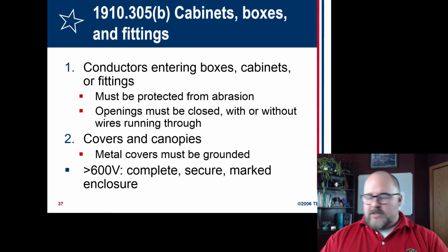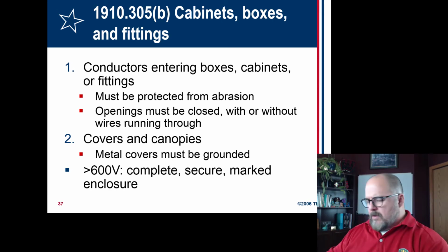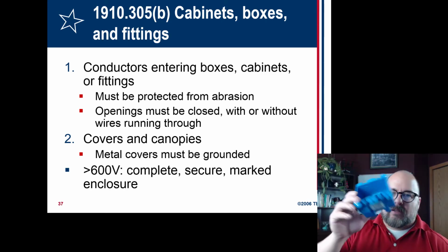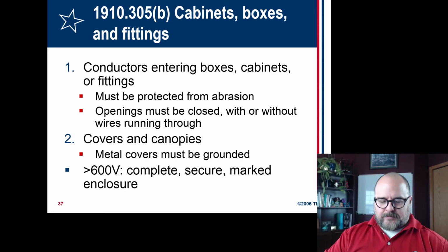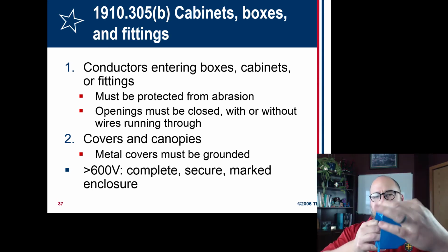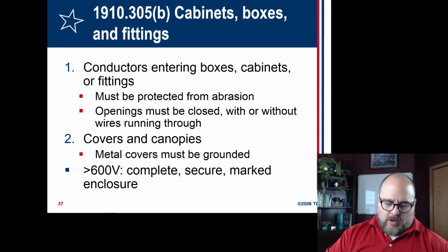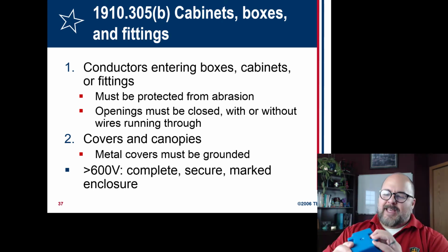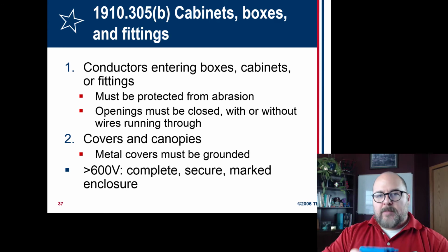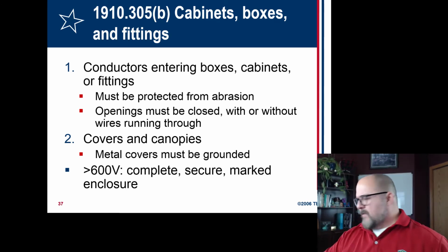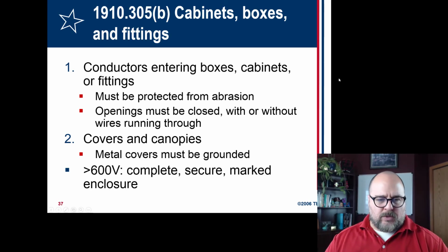Cabinets, boxes, and fittings. It depends what you have in the wall. I've got a bunch of stuff here. So this is a remodeling dual box, because I can cut a hole in the wall and then I can screw this in, and this snugs up against the back of the drywall. And then I run my lines through these. They're a knockout, but they pinch it, so they provide some protection. Versus, I've got some other stuff I'll show you later. I don't want to go too much into it.